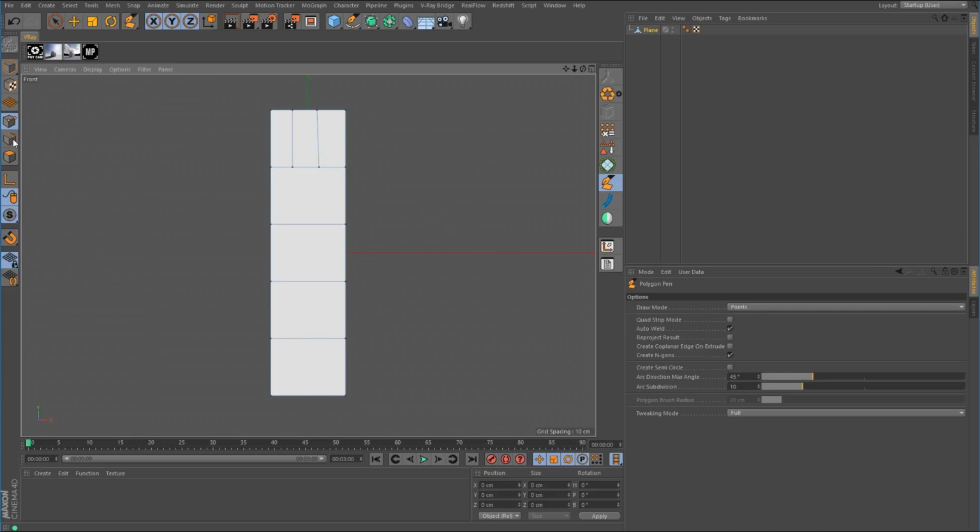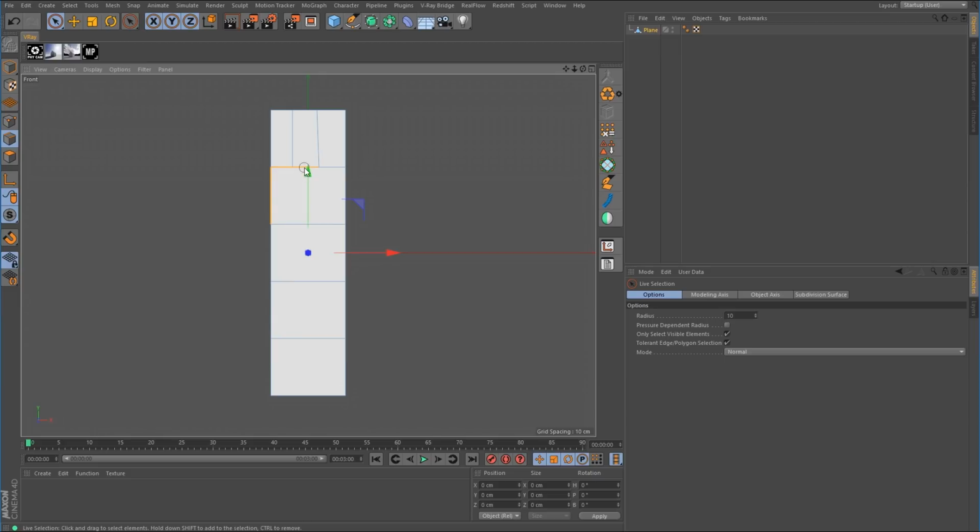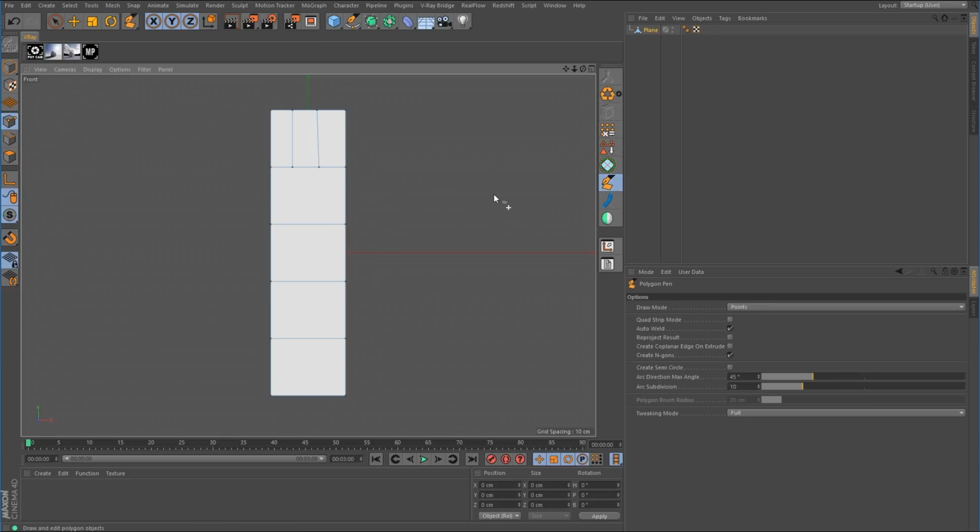We need to solve this because right now this would be 1, 2, 3, 4, 5, 6. This should be a little easier because this is a 6-sided face here, and that's an even number. One way that we could fix this, because we're going 3-to-1, is to make a horizontal cut across here, take these two middle cuts and bring them down, and then take these 2 points here and weld them down to the corners, and there we go. So we've gone from 3 to 1, 2, 3, 4 down to 1.